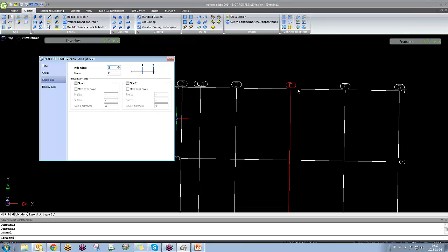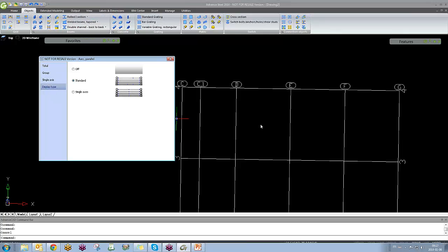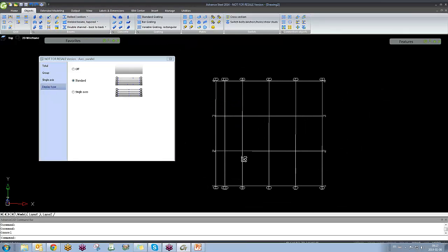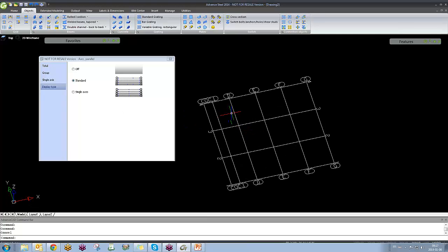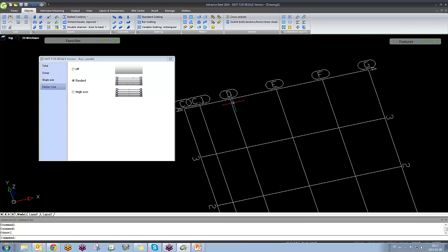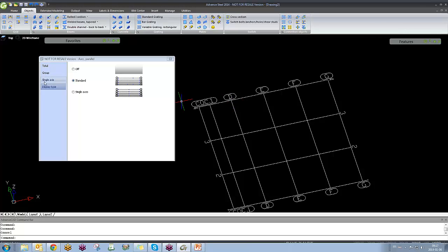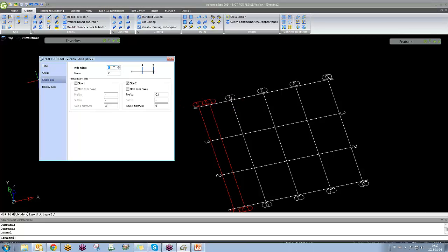Do you see what I mean? Yes, perfect. All you did was highlight the one that you wanted to add another grid line to on either side. Exactly, highlight the single one. If you want to enter it, or just use the arrow, it will highlight it. Okay.